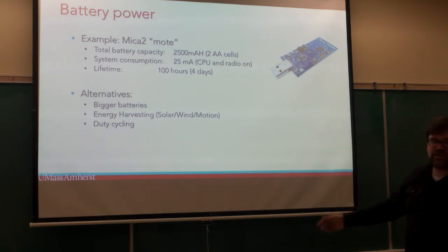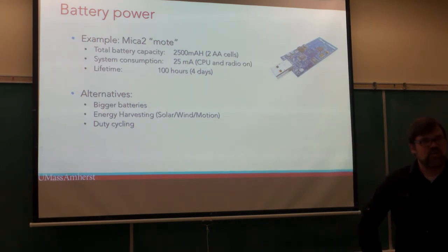So usually what these radios do is something called duty cycling, where they will wake up periodically to see if anybody has anything to send, and if they don't have anything to send, then they go back to sleep. And there are ways that you can ensure that when you wake up, you'll hear the packet, right?